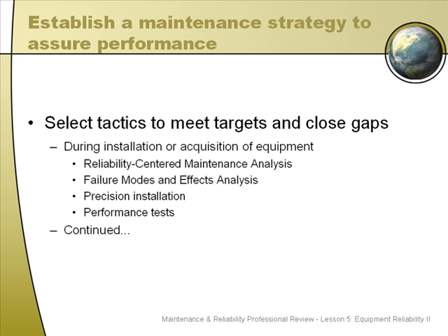First of all, cleanliness. Alignment is very important, and you need to take a look at this because if your alignment procedures at your plant are a few years old, you can find that there are some really good new technology tools out there. Laser alignment's not that new anymore, but there are some really good tools that make it much easier and mistake-proof. But you want to make sure you do a good job with alignment.